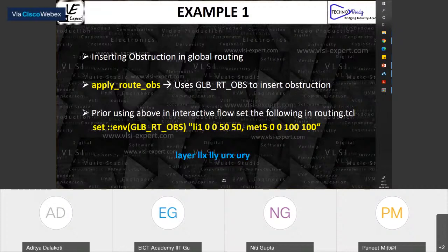So Harish, I'm coming to your question. I'll now try to explain a method of creating an obstruction for routing. I think I need to check whether there is one for placement. Yeah, we can look. You can also look in the OpenLane literature. I think there is no placement obstruction or blockage in OpenLane, but we can definitely check later.